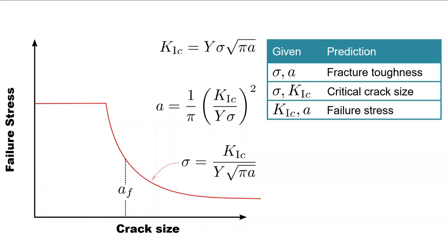As long as the flaw stays below a threshold, then the component will be safe. However, there are limits, as I've described, to this linear elastic fracture mechanics approach. Plasticity enters the stage at this point. Plasticity limits this approach because if we were to purely consider things on an elastic basis, then we'd arrive at an unrealistically high stress for small cracks. This is linear elastic fracture mechanics, after all. So if the far field stress exceeds the yield stress, then all bets are off.